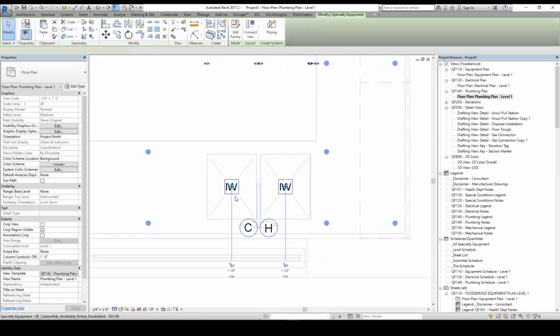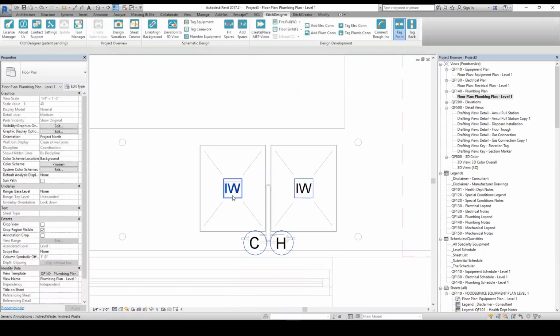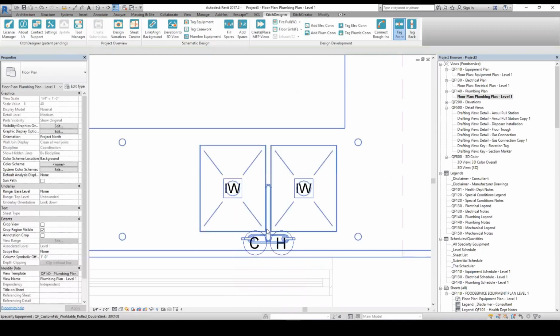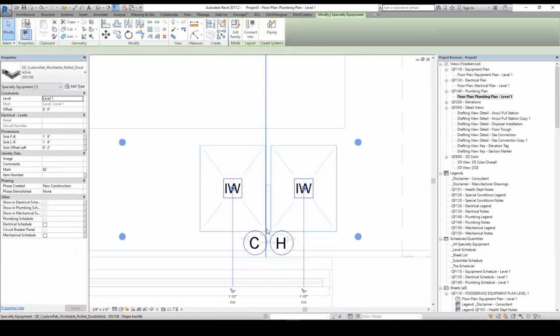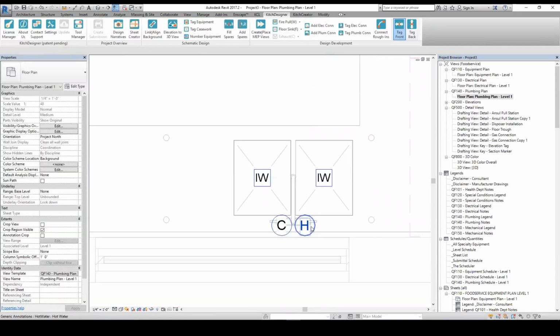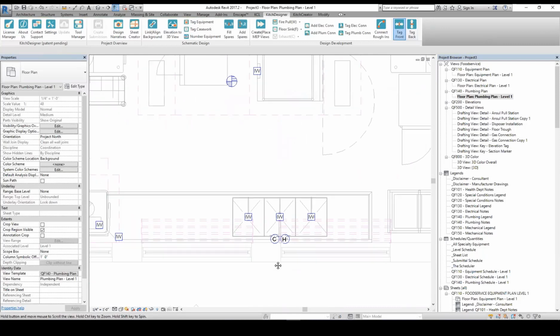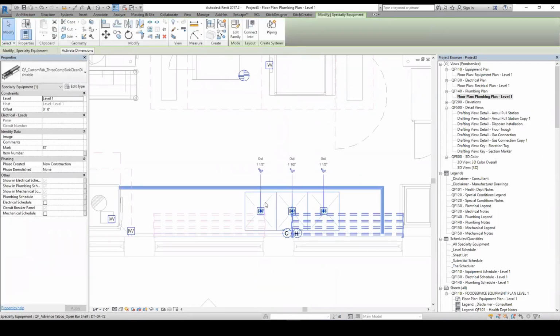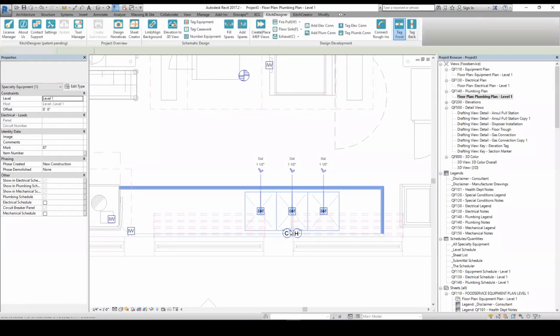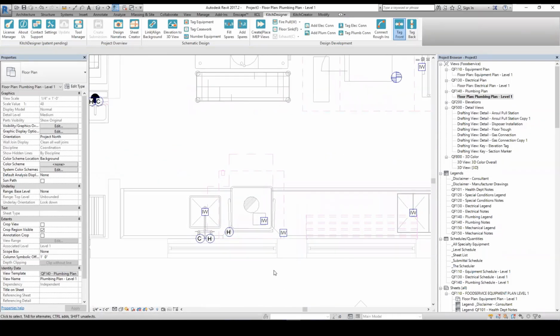And here we have a sink. We've added 2 sanitary connectors on top of the sink bowl, so you're getting your indirect waste right where they need to be. And this faucet, I think this faucet had some connectors. Nope, faucet still doesn't have connectors. So then again, default locations for these hot and cold. So we can go around, you can see it does a really great job. This is because the indirect waste are getting placed because of these sanitary connectors. Looks like the faucets are just using the default rules for when there are no connectors.